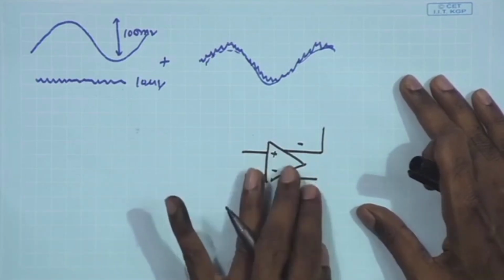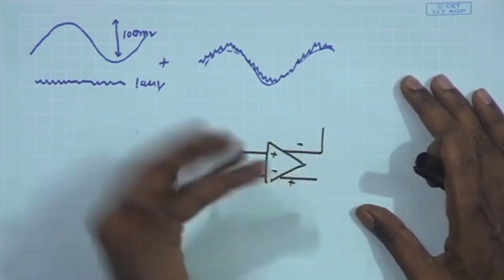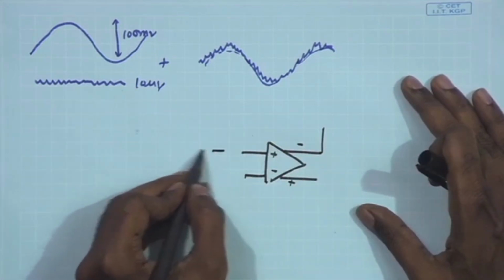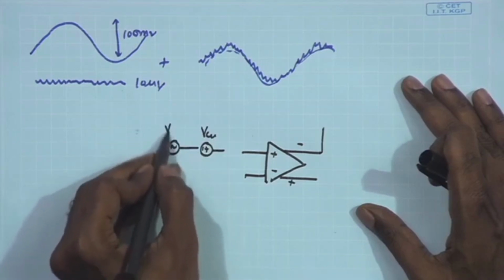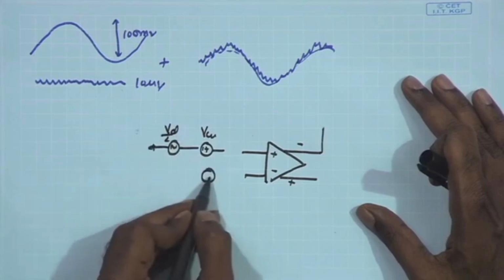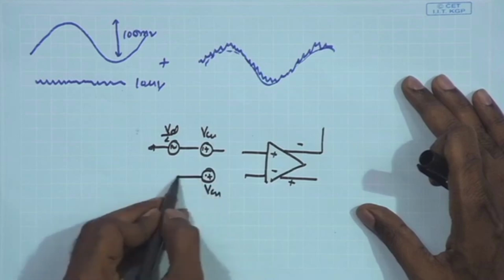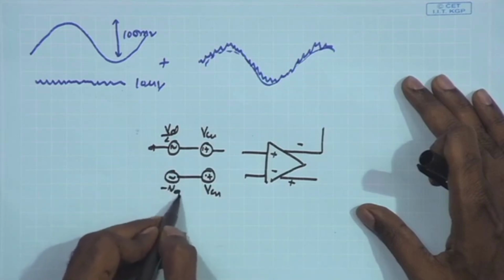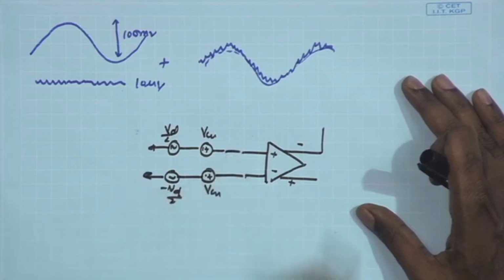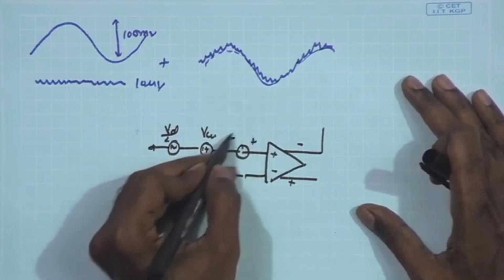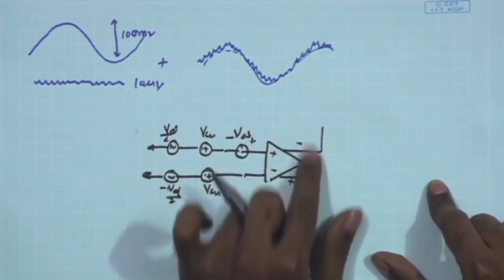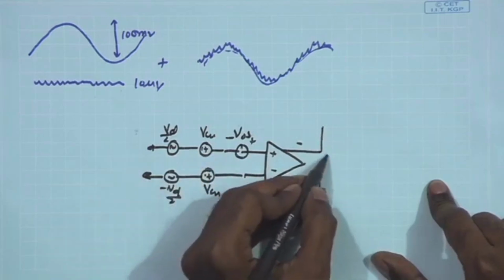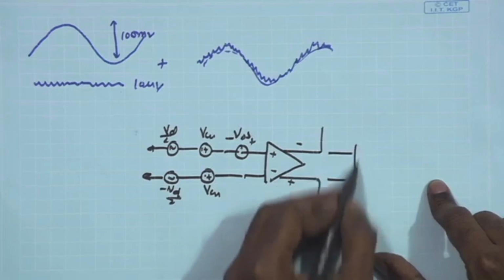So remember, if we do not have the resistive feedback, and suppose you have some DC bias, on top of that DC bias you have some AC signal coming in. So you have some VCM and then you have the AC signal VD by 2, and likewise on the other side you have another VCM, the common mode, and then you have minus VD by 2. These two are applied to the positive and negative terminals, and then one of them is having offset. So suppose you are having a V offset. If you do not have the feedback from output to the input, you have controlled the output DC point using common mode feedback. So this is controlled using the CMFB circuit.